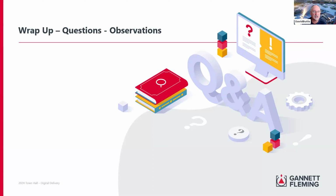But people have to be aware, Sheet Set Manager in itself is 25 years old, and the code was written long before we thought about using the internet as a host and doing cloud-based projects. The code used for that, the XML files and so on, doesn't always play nice outside of a typical Windows SMB environment. It works really well on a local server or local hard drive because of the connections.